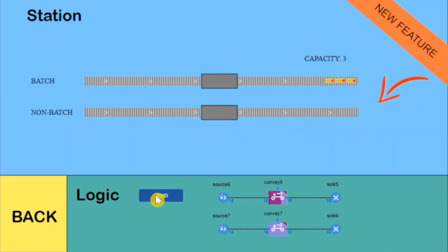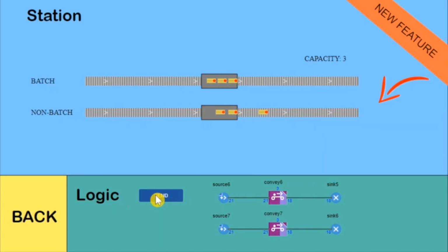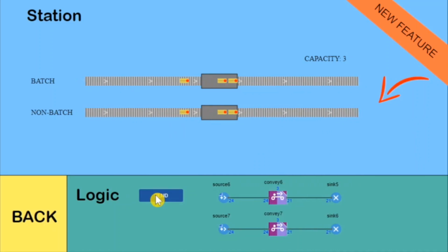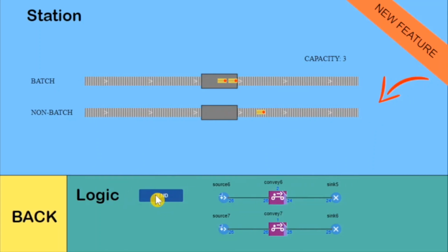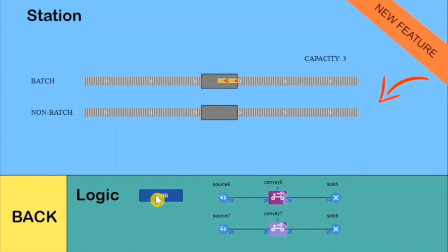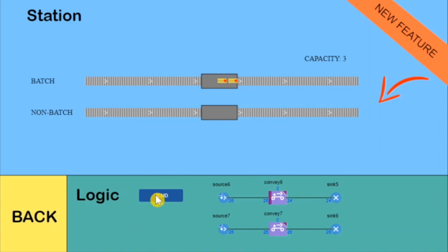In this latest version, a new mode is supported. Processing can now start when an agent enters the station. The station starts to process each material item individually as soon as its leading edge enters the station. For each material item, the processing will last for the specified time. During processing, the material item keeps moving through the station until it reaches the exit, where it stops and waits until the processing is completed.